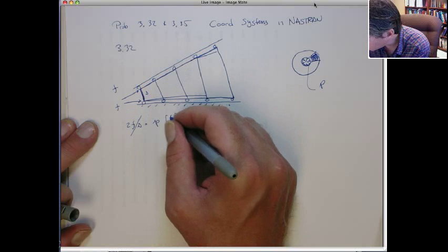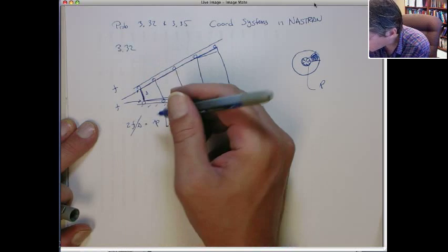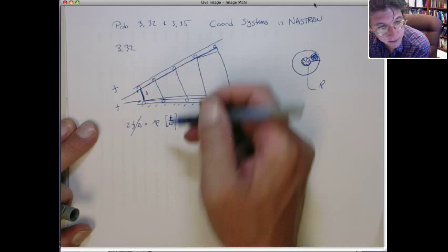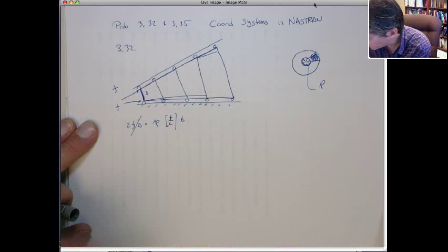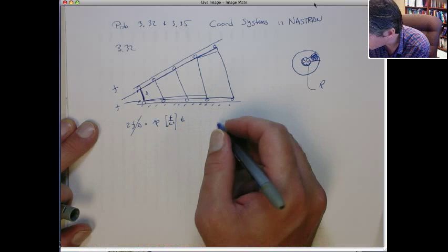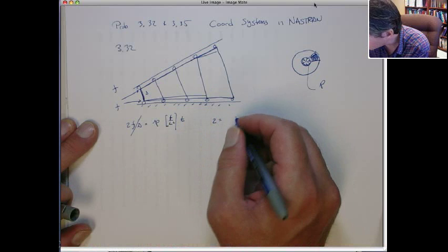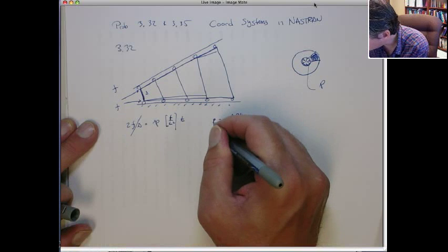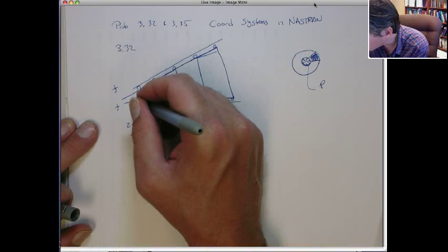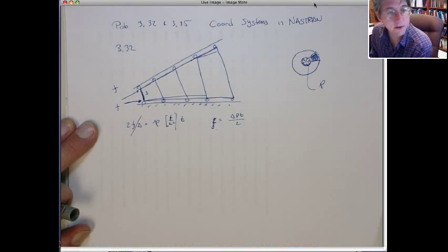Because it's for this length. If it's given to you in force per area, then you have to use the thickness to get out the length, right? If that's in force per area, then it would be the pressure times the thickness, right? So you can get that F is going to be equal to S times P times the thickness over 2. Right? That's the nodal force applied to each one of these nodes. Okay? We talked about the distributed loads before, and you can review that if you're not sure about how we get the 1/2. All right.